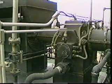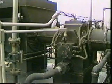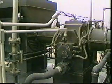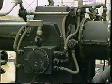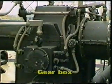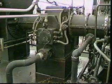In compressors driven by electric motors, speed is generally limited to around 3,600 RPM. In these cases, the electric motor may be coupled directly to a low-speed centrifugal compressor. To operate the centrifugal compressor at higher speeds, the motor must be coupled through a speed-increasing gearbox. This is known as a gear drive. The gear drive and coupling configuration is often used in the oil and gas industry.